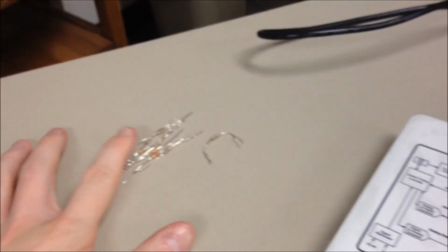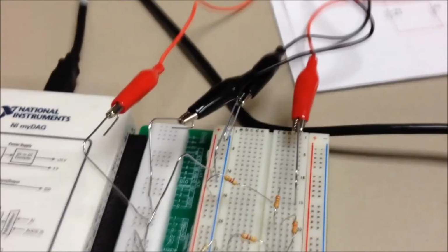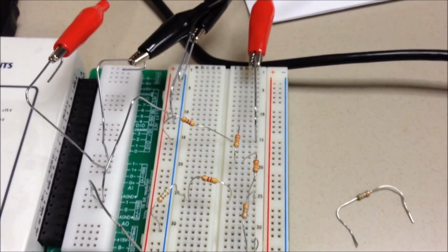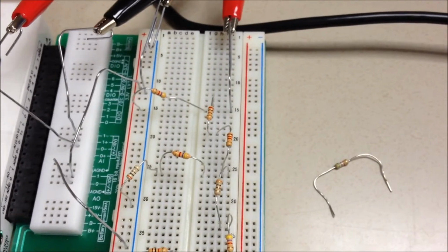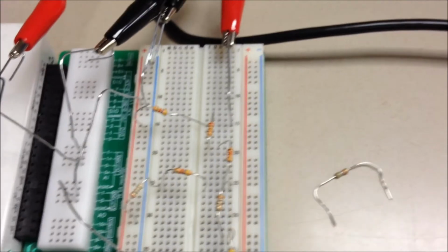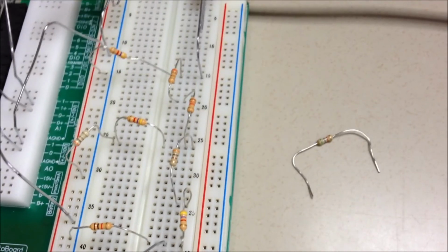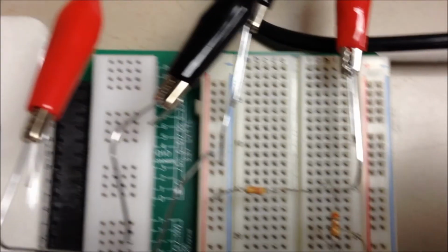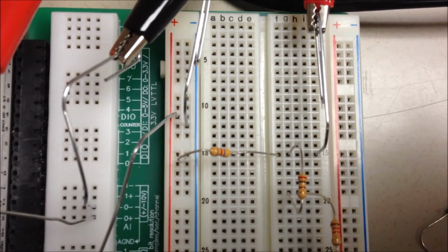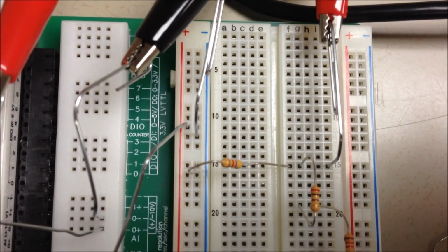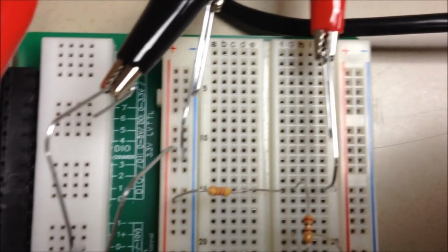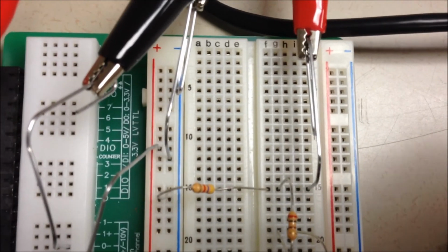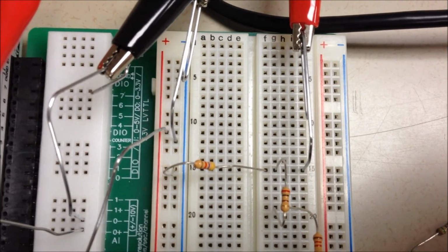So what the lab instructs us to do is have these 10 different values of load resistors here, all the way from 1 ohm to 5.6 k ohms. I would recommend including 3.9 k ohms, which is the value of our R Thevenin, somewhere in that sample of resistors, and you connect them across where terminals A and B would be, so the same place our last load resistor was at, and just measure the voltage across those terminals.